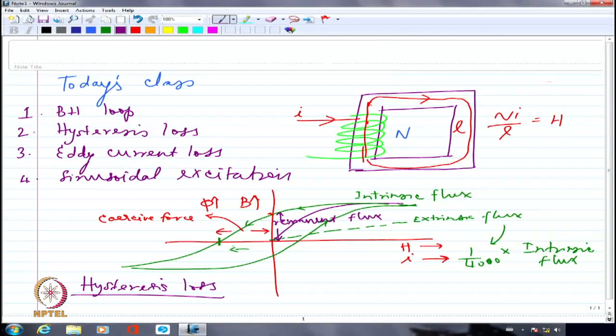So that is really not going towards any productive or useful work, but it is establishing the magnetism in one direction and the reverse repeatedly. That's all it is doing. So this is unavoidable as long as we use a ferromagnetic material, because it has this inherent property of flux lagging behind the current. So this hysteresis property gives rise to a loss called hysteresis loss.